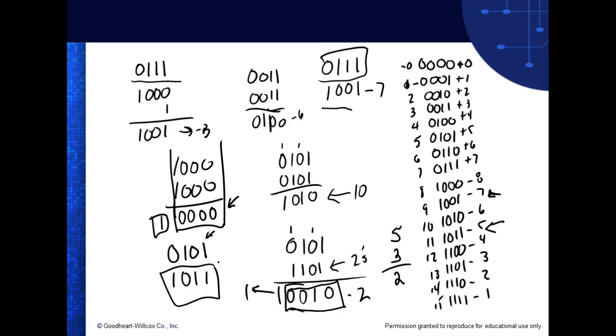But what's nice about two's complement is that you can do the math and ignore the carry. You add this 5, and this right here is the representation of a negative what? A negative 3. So this is a positive 5 and a representation for a negative 3, and what did I do? I just added them together, and I came up with a positive 2, which is what 5 minus 3 is supposed to be, right?